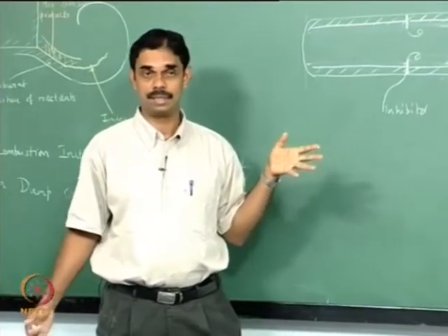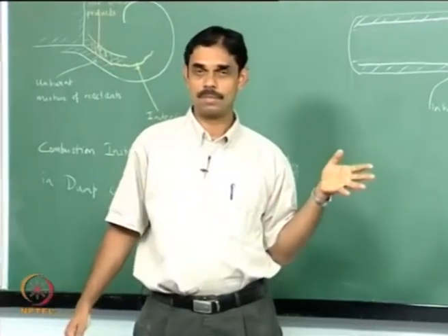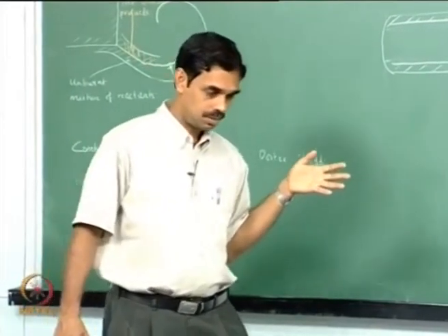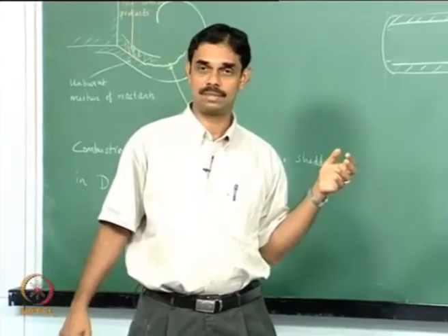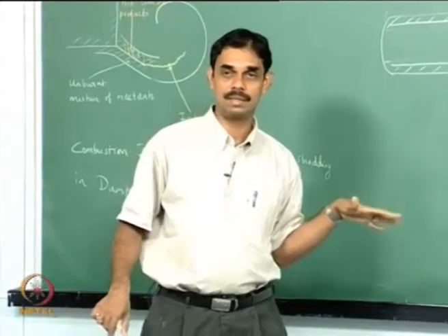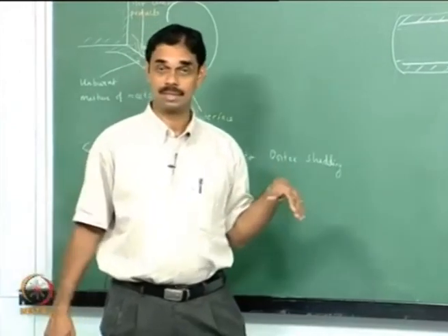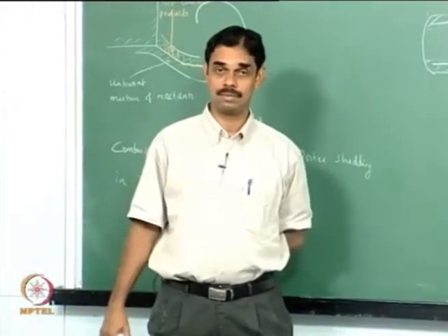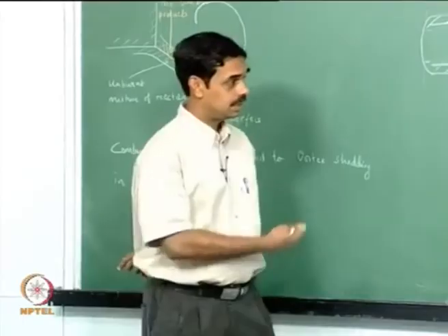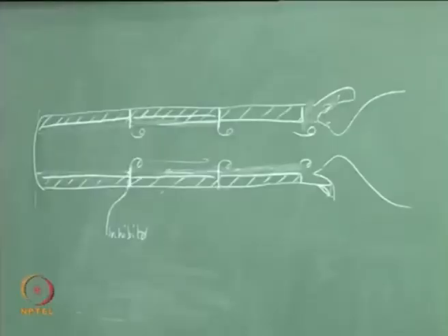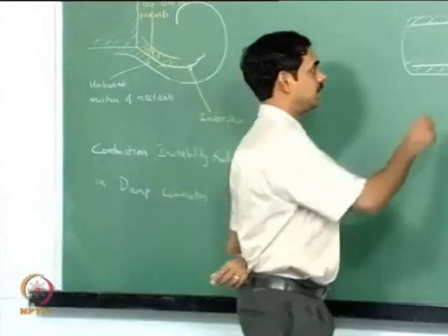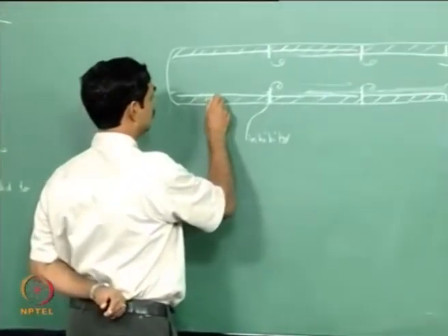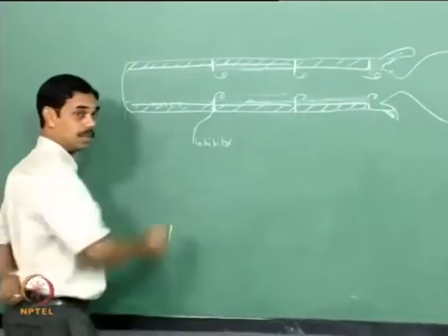So we have to check if, I think we can probably tolerate 0.1% of pressure oscillations or 1% of thrust oscillations. So if they are below that, then the motor is okay, but anything more, I think the motor would be unsafe. So here is another case where this coherent structure is creating a problem, but it's more like an aerodynamic instability. So we are not having, the combustion is all happening just over the propellant surface.